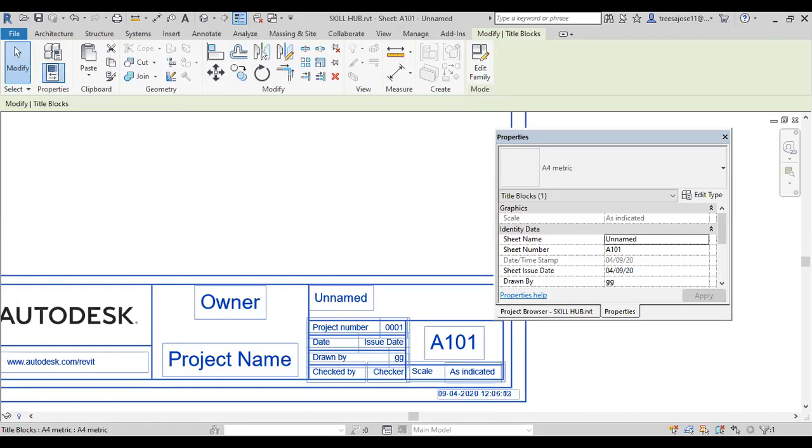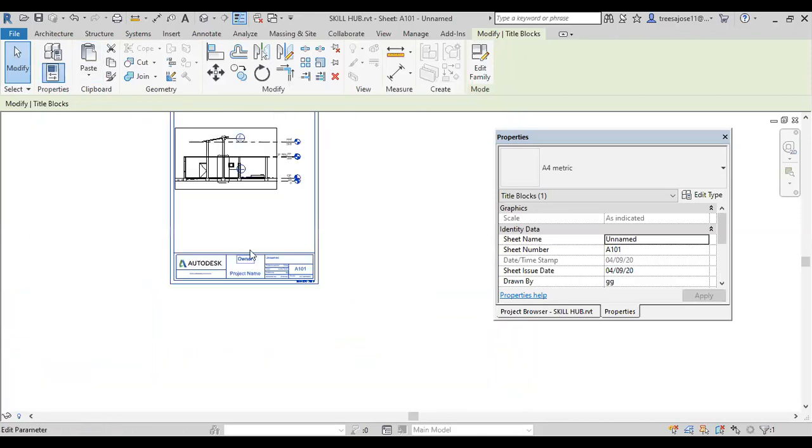I think better in the case of submissions and all, you have to create that submission template, because the submission templates give the area details, floor area, and architects, and some standardization will be there. You have to create that one first. Then instead of adding this A4 sheet, you drag that particular template.